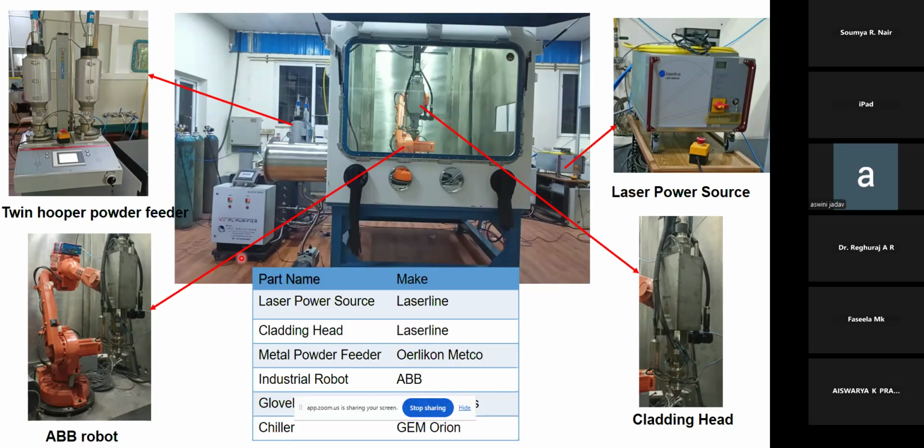The powder which you are supposed to use in this machine can be any powder like aluminum alloy, stainless steel, titanium, or super alloys, but the powder size should be less than 80 micron and above 20 micron, 20 to 30 micron, right? Normally, what is available in the market has a size of 40 to 80 micron. So those standard powders can be used in this machine.